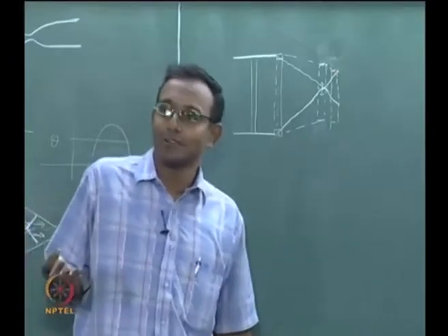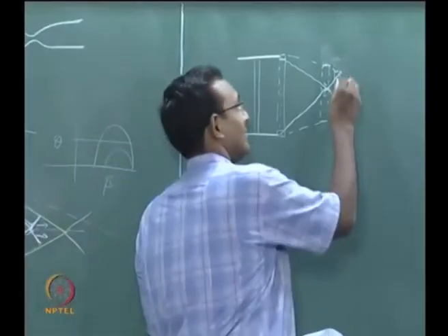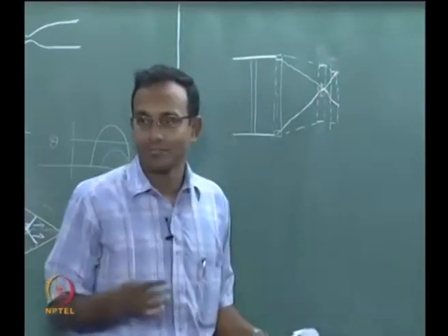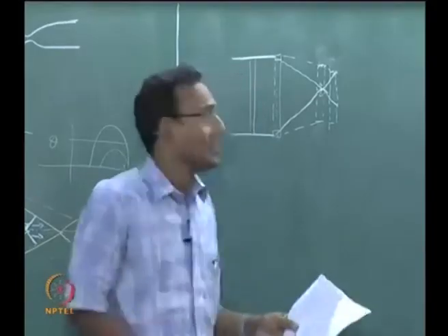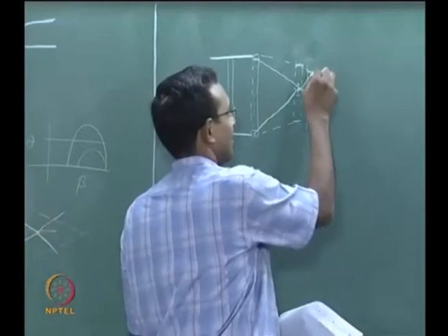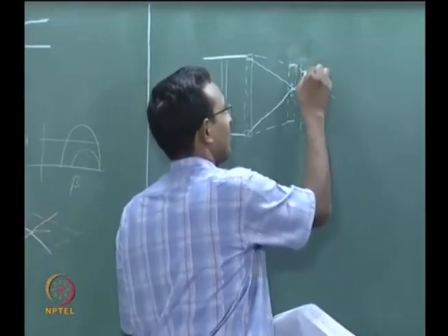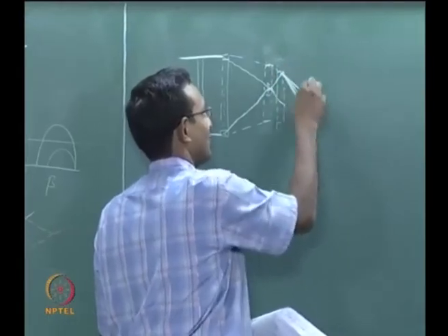Now what will that messenger do? He has to run, he will again start running. He is going to say decrease pressure by so much, and typically it is done by a whole bunch of expansion waves, and they do not go all together like a shock, they go each individually. So there will be a whole set of fan of expansion waves running out.